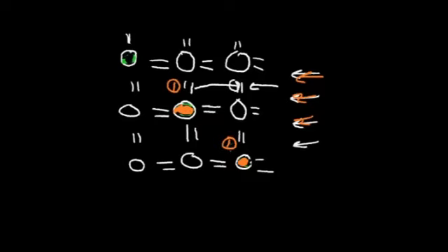And so to summarize, we can change the silicon crystalline structure by adding impurities. For example, boron will make it a P-type silicon. Phosphorus or antimony or arsenic, which has 5 outer electrons, will give us a surplus of electrons and make it an N-type material. We'll talk more about P and N-type in a future video.